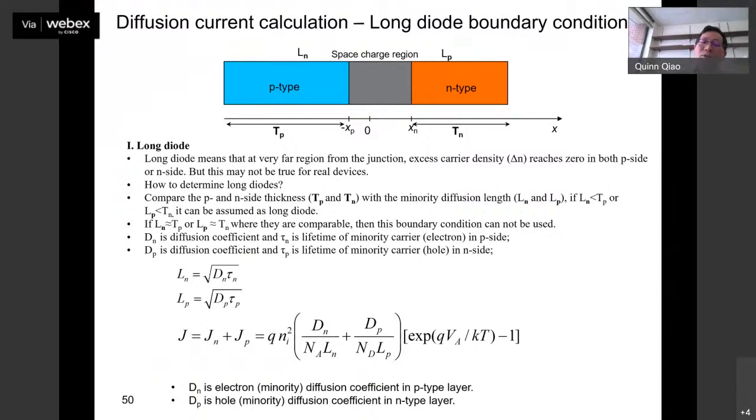So once you know your device structures, you basically want a lower gain, right? You talk about that gain, you talk about saturation current not being flat. That's basically because you have shunting there. You have shunting as there's different bias, especially as it goes to negative bias. Suppose the ideal case is that all the charge on the inside cannot go to the P side, right? But now since you have shunting and tunneling there, charge flows there. There's electron-hole recombination there.